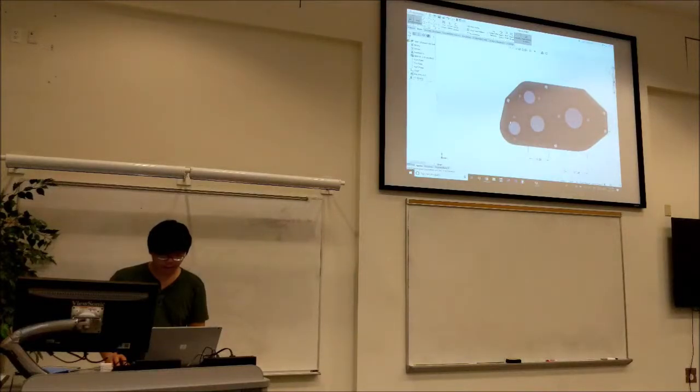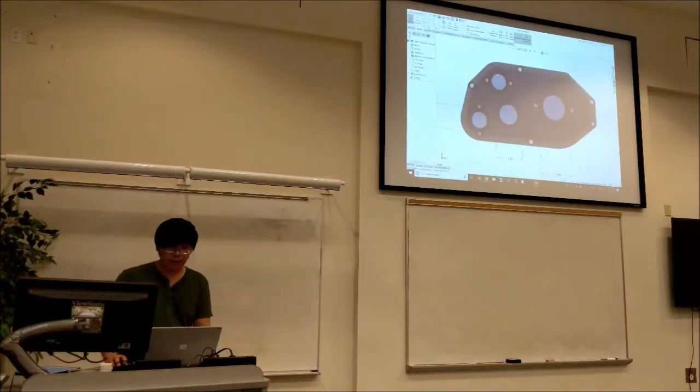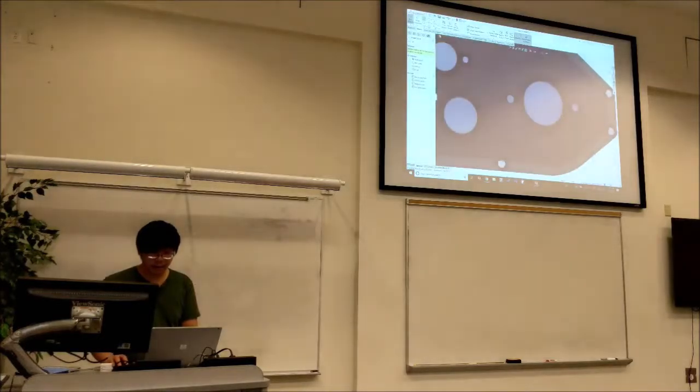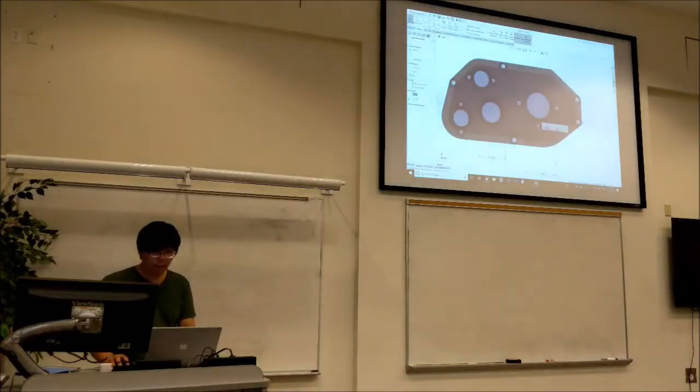For this, I think 1 inch should work. So we're going to keep material all around this, right? But if we cut extrude now, these are just going to be free floating. So this is where we use construction geometry to connect this up. We're going to draw a line here to here, right? And then eventually we'll use offset entities, and it'll expand the line.